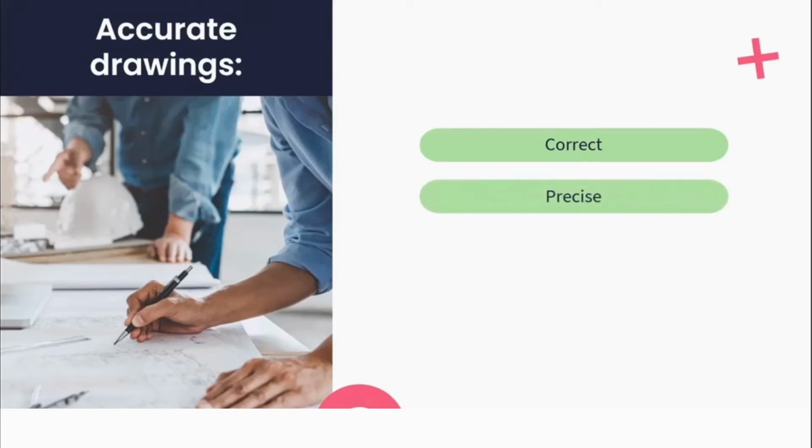Secondly, precision or precise placement. Clarity and precision is of utmost importance. Dimensions must be placed in the appropriate position in relation to what they are indicating measurement for. Then completeness. Nothing must be left out. Nothing must be duplicated and nothing must be left to the imagination. That dimension needs to be complete.